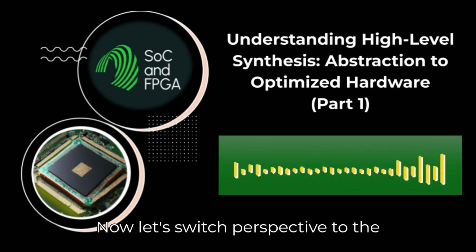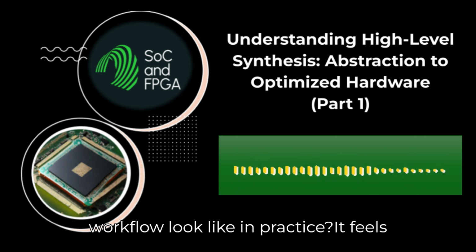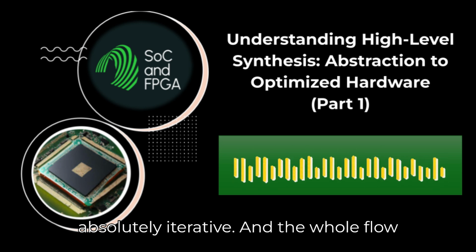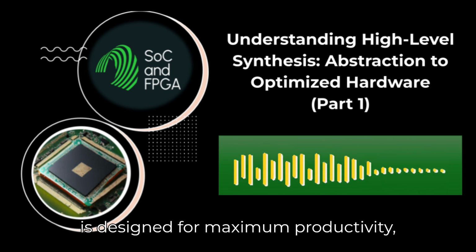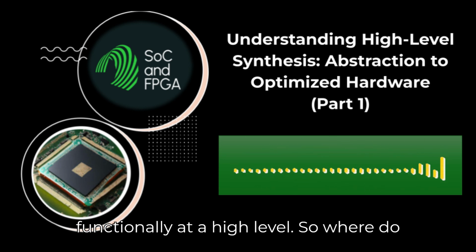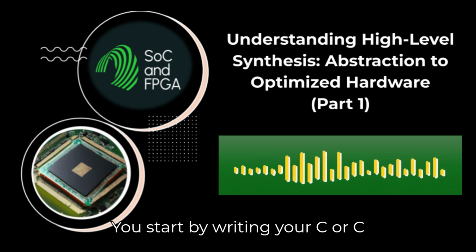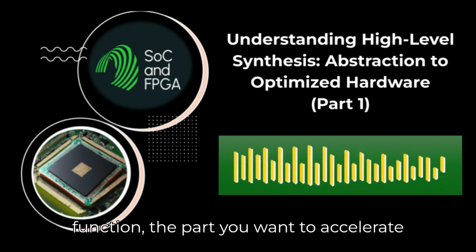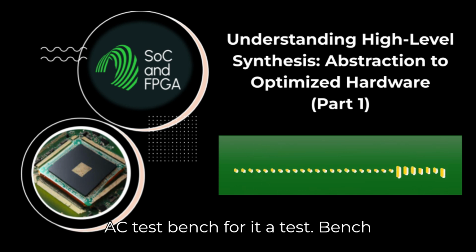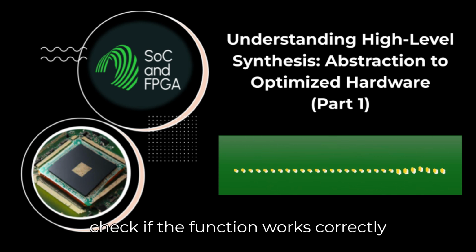Now let's switch perspective to the developer. What's the actual HLS workflow look like in practice? It feels like it must be iterative. Oh, it's absolutely iterative. And the whole flow is designed for maximum productivity, really leveraging that ability to verify functionally at a high level. So where do you start? Writing C++. You start by writing your C or C++ function, the part you want to accelerate in hardware. And crucially, you also write a C++ test bench for it. A test bench, just like in software development, to check if the function works correctly.